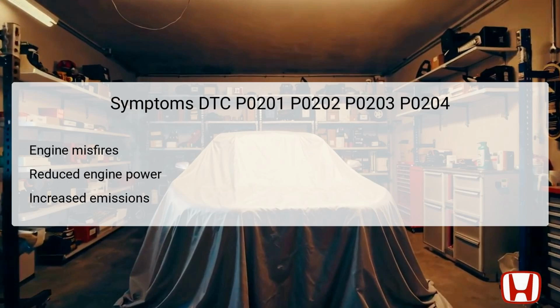Reduced engine power is a direct consequence of inefficient fuel delivery, making the vehicle feel sluggish and unresponsive. Additionally, increased emissions may result as the fuel-air mixture becomes unbalanced, causing the vehicle to fail emissions tests if not addressed. Recognizing these symptoms can aid mechanics and technicians in isolating the problem effectively.